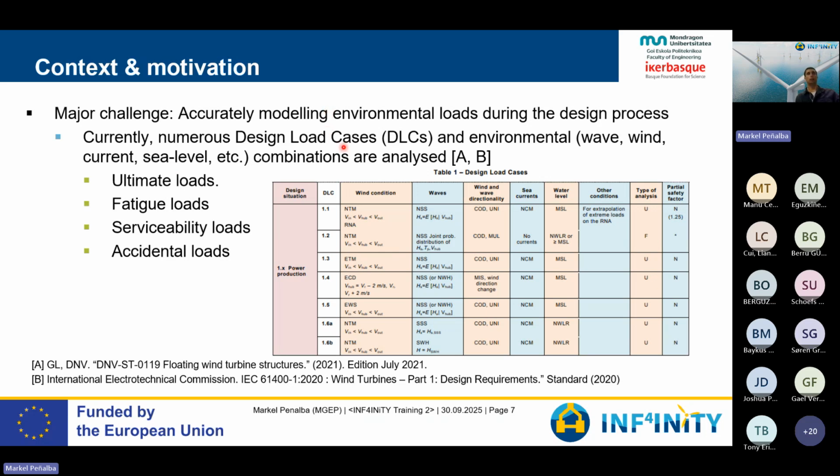So to that end, what we usually do, and this is based on different standards, but the most common ones are the DNV and the IEC standards that I've shown here. They divide it into different conditions or different cases. Ultimate loads, which is more related to the extreme environments, fatigue loads, which is related to the operational environment, serviceability loads, so conditions where we have to perform some services, and then accidental loads, which are also maybe not that common, but at least present throughout the whole lifetime of the wind farms.